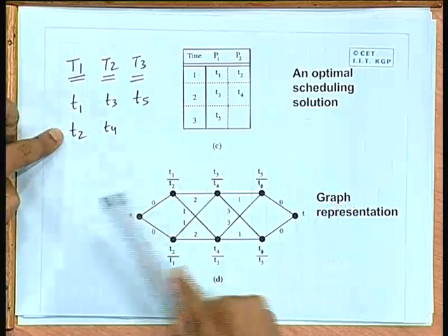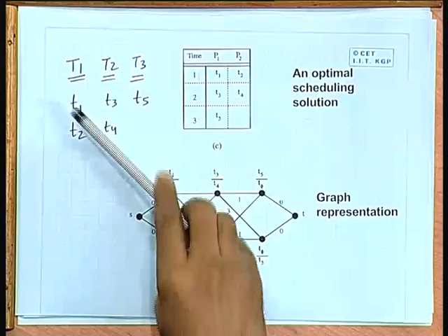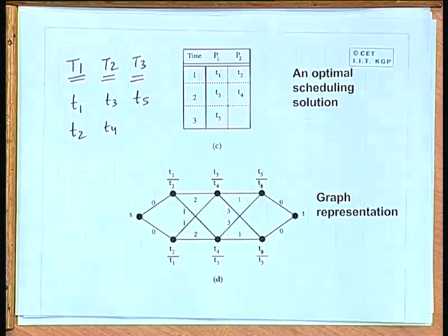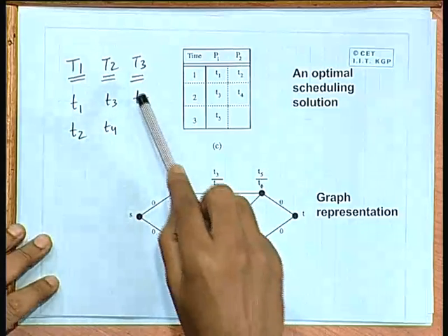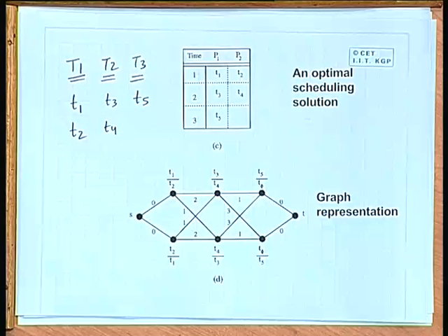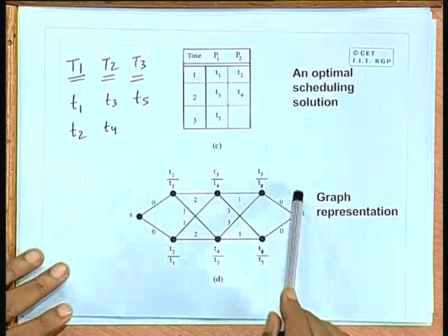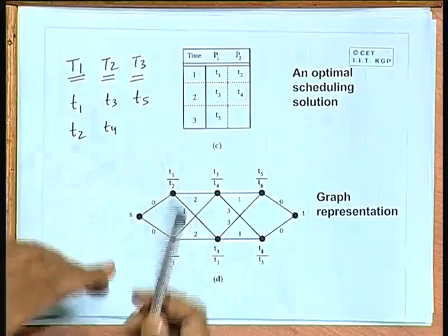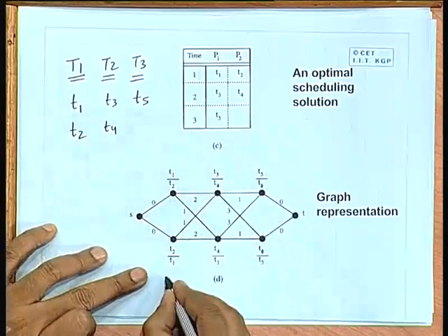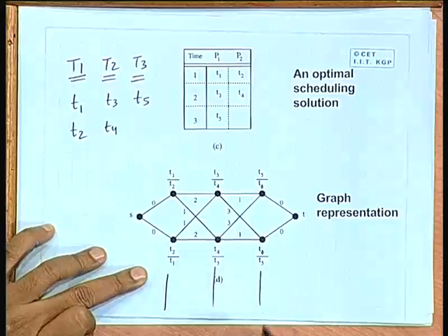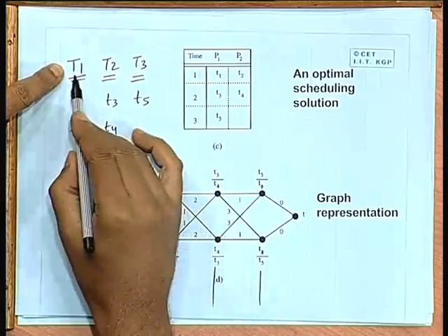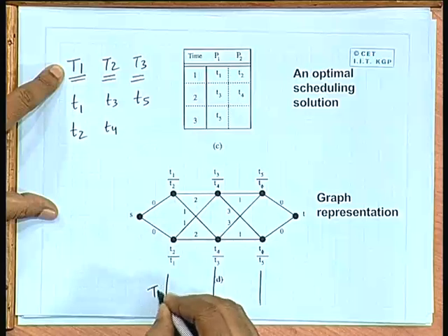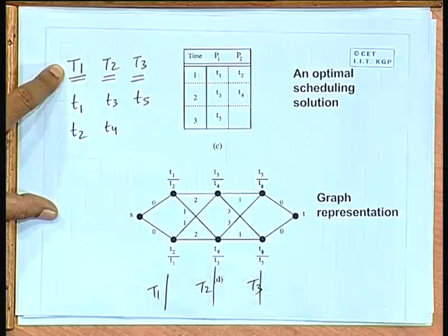But now we have a choice. There are 2 layers, one on top of the other. So, either I can put t1 on top and t2 below, or t2 on top and t1 below. Even on the same track, I can put this above this or this above this. Similarly, t5's other slot is empty, so I can put t5 on top or on bottom. So, I construct another graph where each level, level 1, level 2, level 3, indicates these super composite tracks T1, T2, T3.